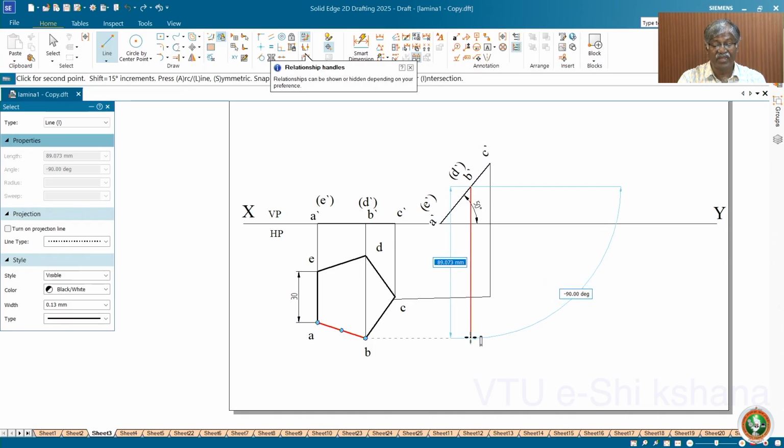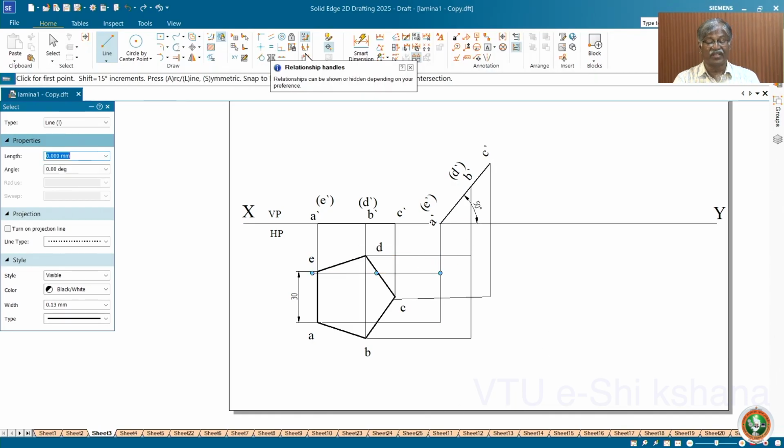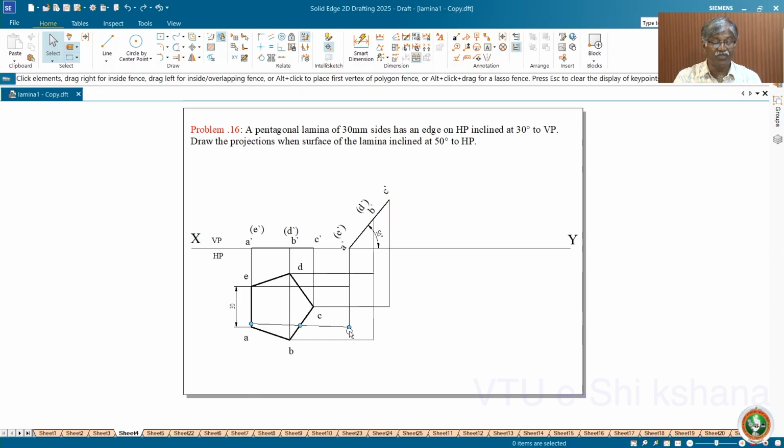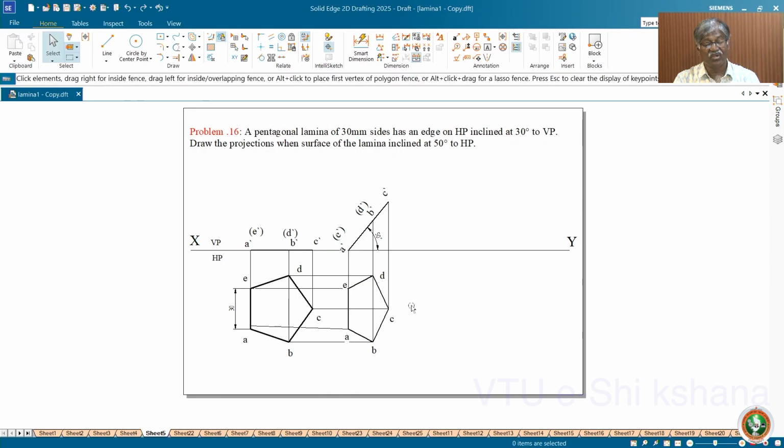See, this is for BD. You take D as reference, B as reference and draw this line. Again, this itself gives you D on the same line. Next extreme A is here, lower, and touch with this A. Draw. Then C. Unnecessary projections you avoid. You do only this. Now, assume that I have done that job and then name these points as A, B, C, D and join this and you get the final top view.